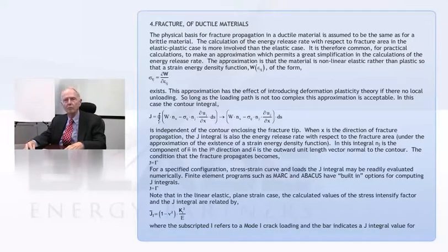So, armed with all of that, people then cooked up an equation like 4-1. So, in regular elasticity, the stress-strain equation can be written in terms of the partial derivative of the strain energy with respect to the strain, and that'll give you the stress. And that's a quick way to get the stress-strain equations if you happen to know the expression for the strain energy function. Well, what's been done here is they say, well, okay, now we're going to make this nonlinear, and we're going to make the curve bend over, just like a plasticity curve. If you do that, then this opens up a lot of doors, and one of the things you find everywhere is the use of the so-called J integral, and this J integral is a big deal.